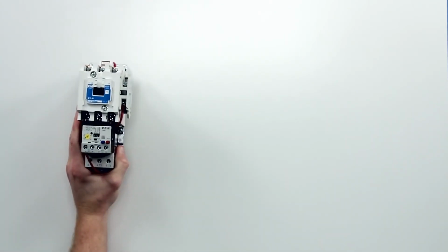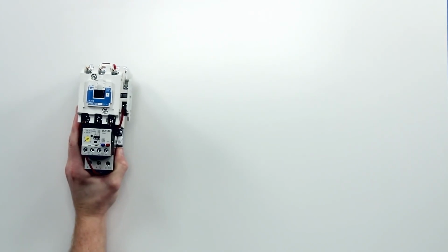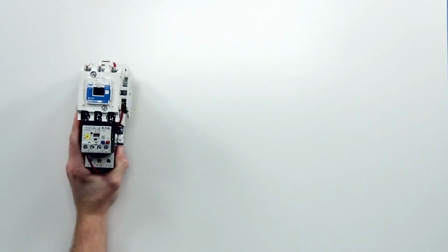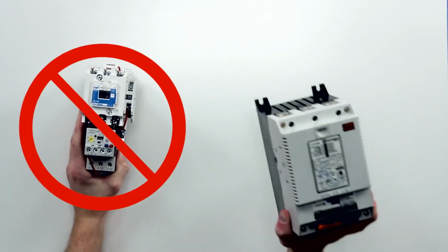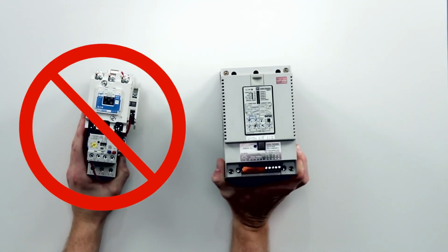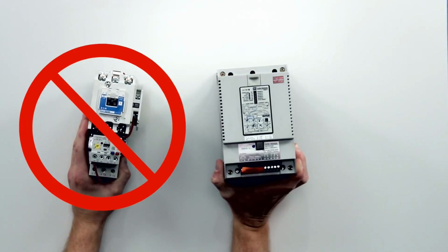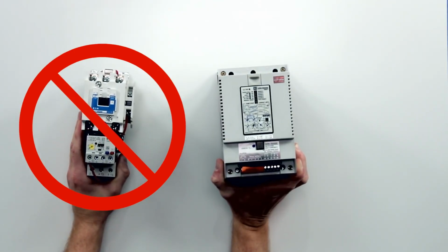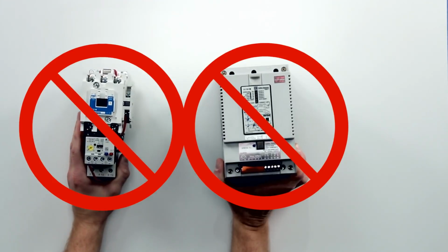How do customers control industrial motors? Well, traditionally, customers use our trusty friend, the full voltage starter, which applies the full line voltage to the motor when it turns on. When a full voltage start is too harsh or accelerates too fast, we could use a soft starter to reduce the voltage sent to the motor and slowly ramp it up to full voltage. But with both of these controllers, once we get to full speed, the motor is stuck there until we turn it off.